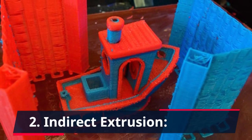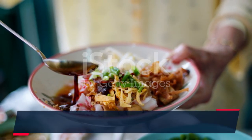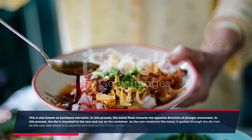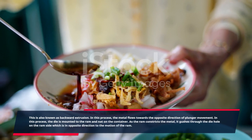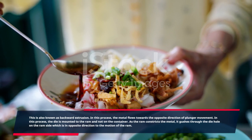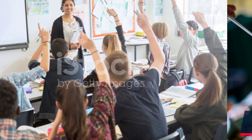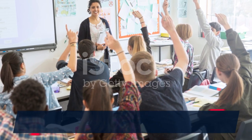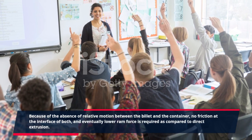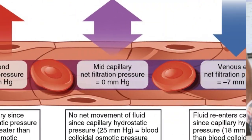2. Indirect extrusion. This is also known as backward extrusion. In this process, the metal flows in the direction opposite to the plunger movement. The die is mounted on the ram and not on the container. As the ram compresses the metal, it gushes through the die hole on the ram side, which is opposite to the motion of the ram. Because there is no relative motion between the billet and the container, there is no friction at the interface, and eventually a lower ram force is required as compared to direct extrusion.